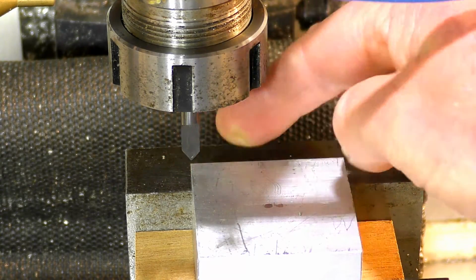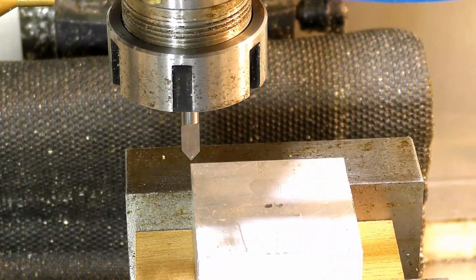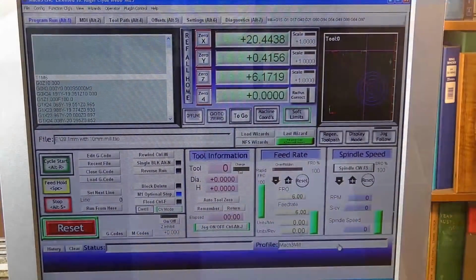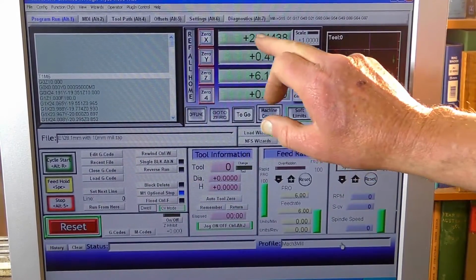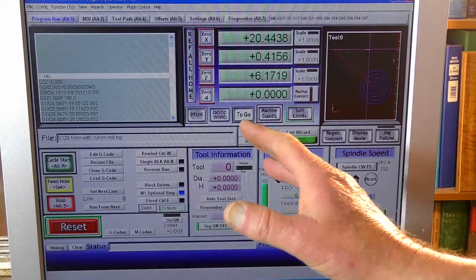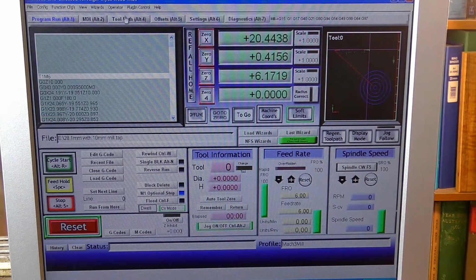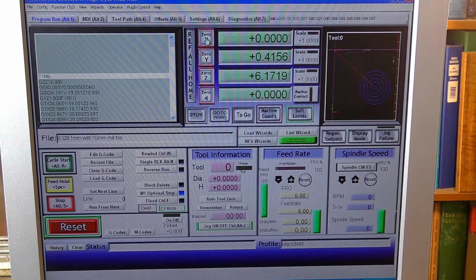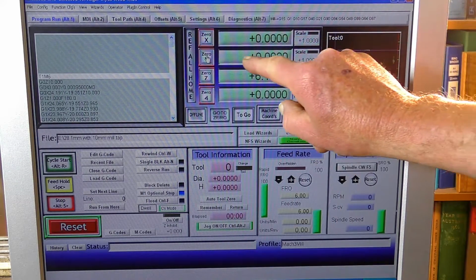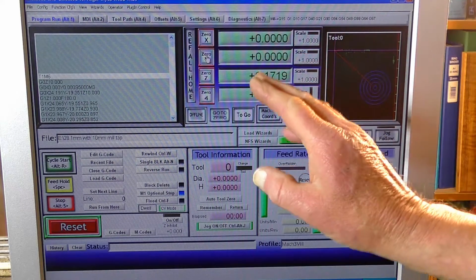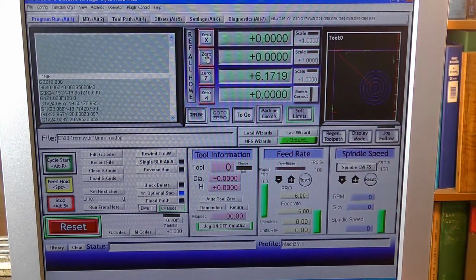That's telling me right in that corner. So now I can set the XY coordinate. Now to set the X and Y coordinate to that 0 position, very simply you go here, press the X, press the Y, and you get your 0, 0 point, the start of the program.